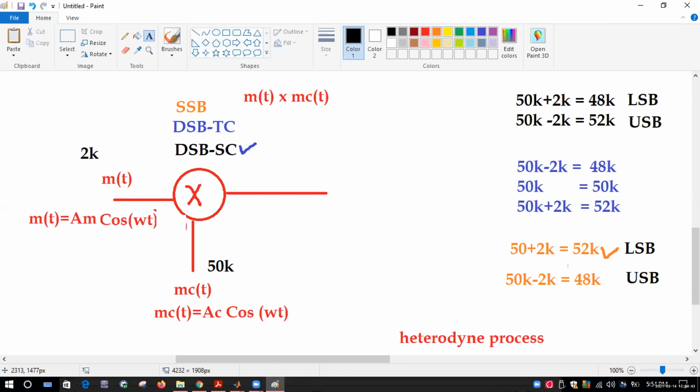Why? Because if you send both of them, both frequencies will consume a lot more power. But if you use only one for sending out the signal, then it will consume half of the power. It means if your battery lasted for 10 hours, now this one will give you 20 hours, because it's consuming less power from the battery. Do you understand the concept now?